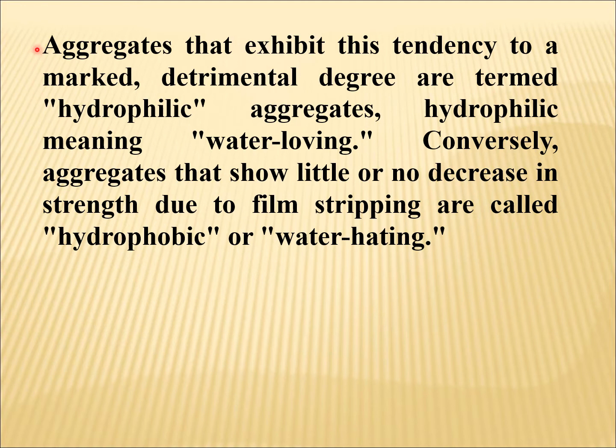So the aggregates that exhibit this tendency to a marked detrimental degree are termed hydrophilic aggregates. Hydrophilic means water-loving. Conversely, aggregates that show little or no decrease in strength due to film stripping are called hydrophobic, or water-hating.